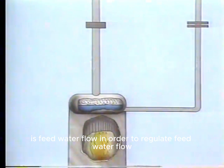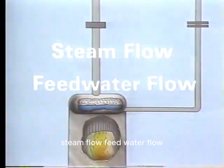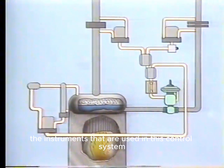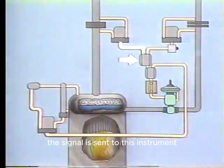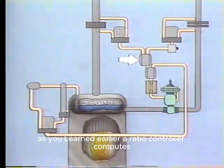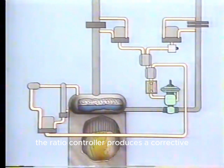In order to regulate feed water flow, the control system needs to measure three variables: steam flow, feed water flow, and drum level. To see how this is done, let's add the instruments that are used in this control system. This transmitter measures the flow of steam leaving the boiler and produces a signal that represents that value. The signal is sent to this instrument, which is a ratio controller. As you learned earlier, a ratio controller computes the ratio between two signals. If the two signals do not compare at a predetermined ratio, the ratio controller produces a corrective output signal.